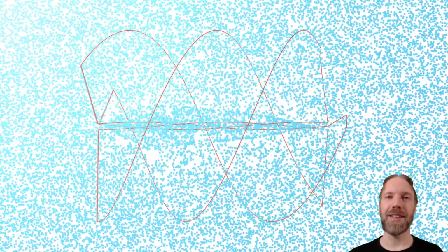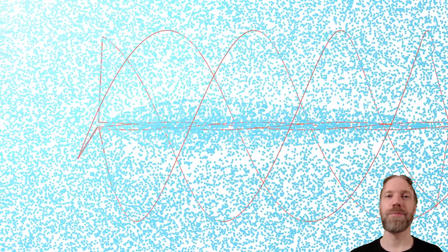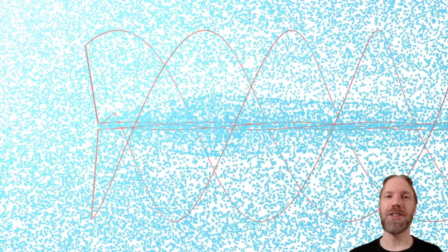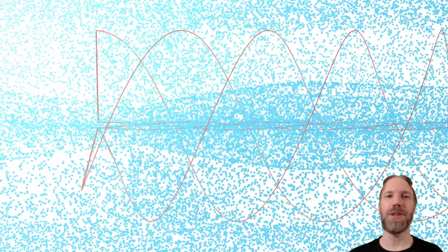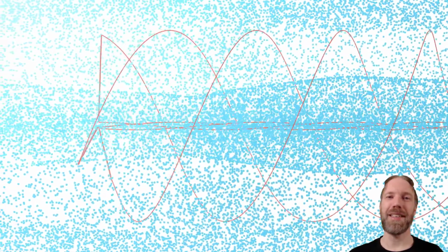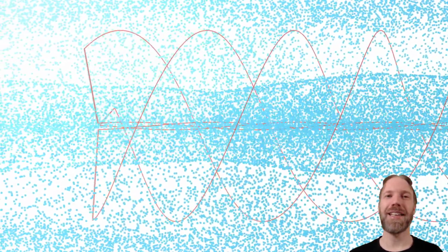We should also account for that the blades are moving in circles and not in straight lines. Here we have a simplified approximation of a rotor. We have the outer tip vortices, and the inner vortices close to the center are called root vortices. I want to remark that this is a simplified model where the entire root vortex is released at the same position. But in reality, as we do not have optimal chord all the way to the center, the root vortex will be distributed over a larger area. Hence, the wake rotation is slightly overestimated in this simplification. I have also neglected wake expansion to make it visually easier to follow.